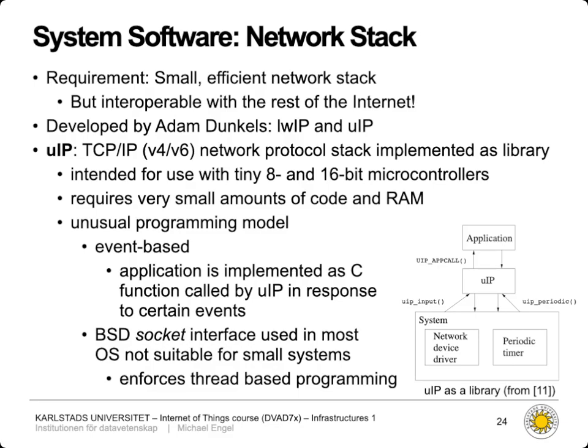And it also helps to keep the operating system and the IP stack in control, because if you don't have preemptive multitasking, for example, then an application that would wait for something would not be able to receive network packets. So if we are waiting for data from sensors, we would be unable to receive network packets without any elaborate interrupt handling and stuff like this. So this event-based approach actually helps us to build a simple software structure that can still work and provide TCP/IP on very small microcontrollers.